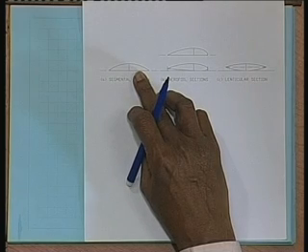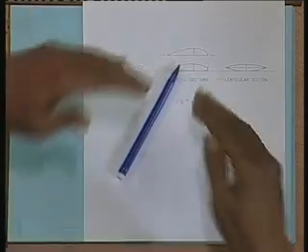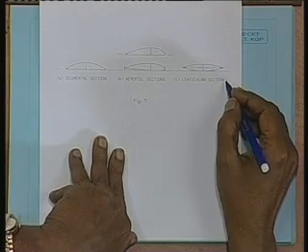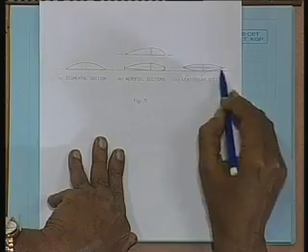In many propellers, there is a combination of both aerofoil section and segmental section. That is, aerofoil sections up to a certain radius, and then the sections slowly change to segmental sections. We will see some of these propellers later on. Then what you have is called a lenticular section, where the section is symmetrical about its center line.